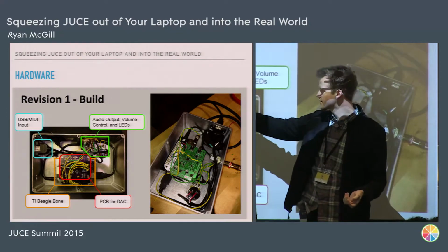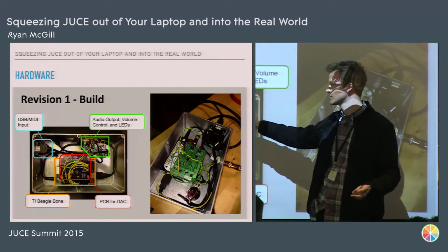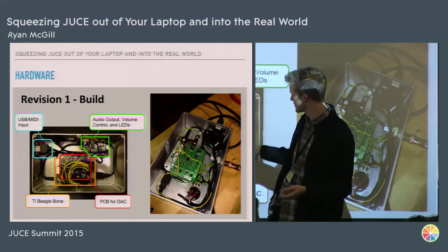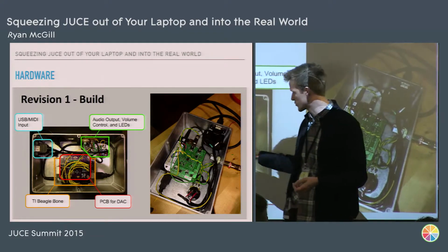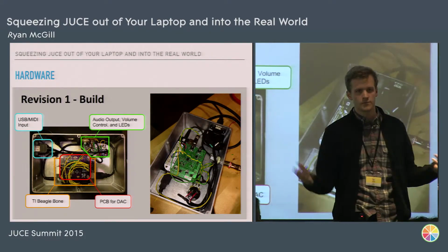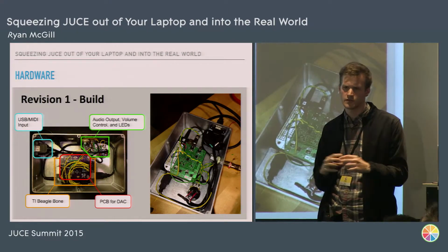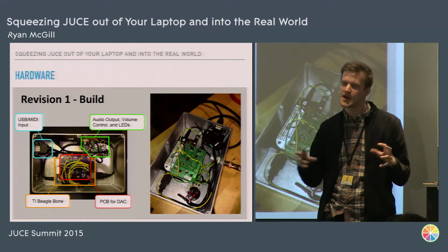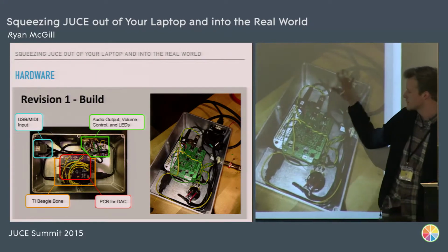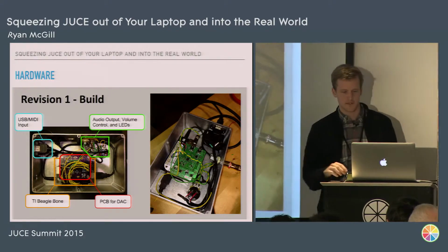And then over here, this is just a volume knob. It's all analog. That's the audio signal coming out into a voltage divider. And this is just a USB extension cable, so this is straight to the USB port on the device. This is so you can plug in whatever MIDI controller you want, or when you're developing, you're going to probably have to plug in some sort of USB device sometimes, like a keyboard or a mouse, just to get the device up and running. This was the cleaner form factor, the second edition that they actually took on tour that was sturdy.